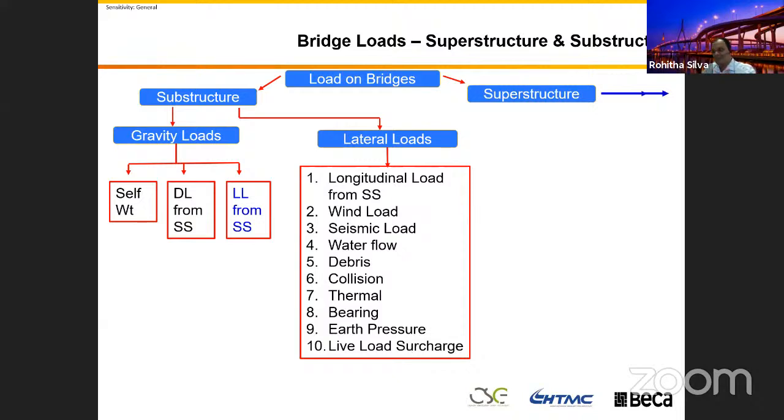So we have two axes. In any axis, the longitudinal or transverse direction, these loads apply on your substructure. So there is a series of loads, and you need to combine them to get the critical load effects.